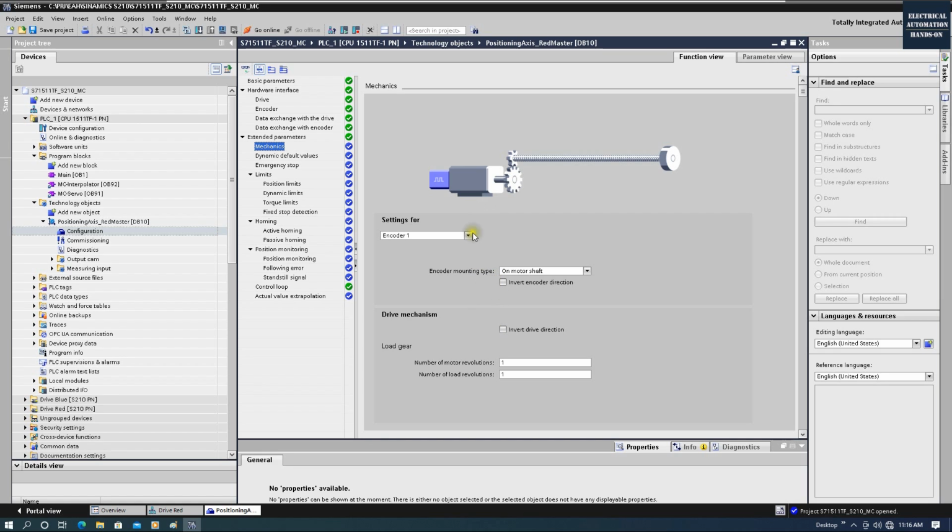So the servo motor and the drive always come together with the same direction. But your load usually has a backward direction. Then you need to invert your encoder, and also invert your drive. Okay, keep this in mind. That invert is very simple, but basically they come together, inverting and activating at the same time. Okay, the mechanicals.